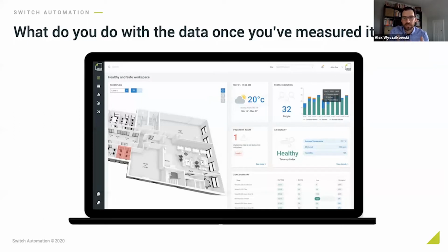One company makes a product that looks at temperature, humidity, CO2, and even VOC levels. So when you do a deep clean, you're going to have some of these volatile organic compounds come off, and you can actually sense that. So that's a sensor that can potentially validate, if you've got that data trended, you can validate the cleaning with that VOC spike. And in the same way, the building also has security access required. So if you want to tap in, tap out, you can access that data and see, hey, did the person that has the key card from the janitorial staff, did they key in, key out?